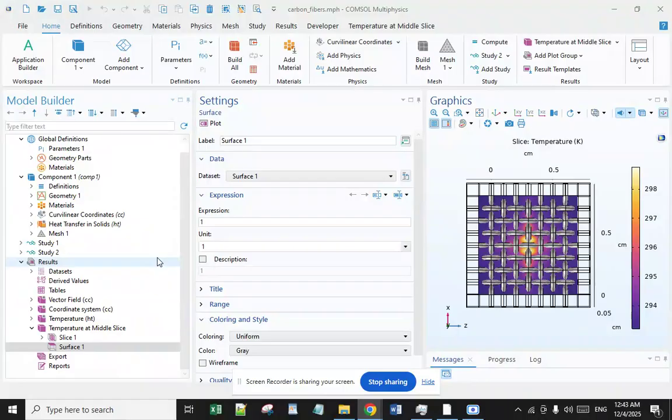The next best constitutive relation for the thermal conductivity of a composite transverse to the fibers is given by this model, where Km and Kf and KT are the thermal conductivity of the matrix (or air for dry reinforcement) and the transverse thermal conductivity of the fibers respectively, and Vf is the fiber volume fraction.